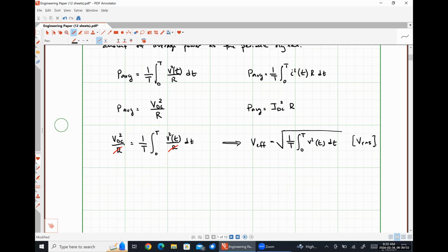So literally the units RMS tell us what mathematical operations to do to our periodic voltage signal in order to get an effective value. We could do an incredibly similar derivation and find that the effective value for a current is going to wind up being the exact same thing, where a current effective value is measured in amps RMS.